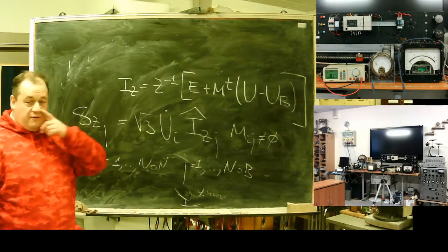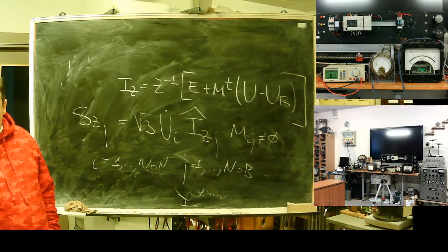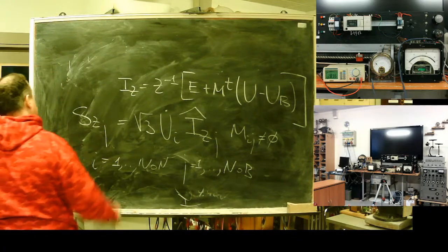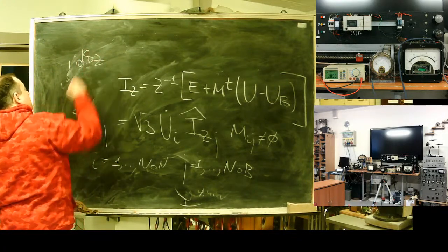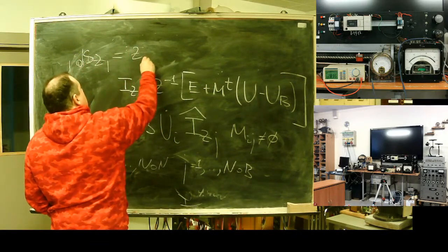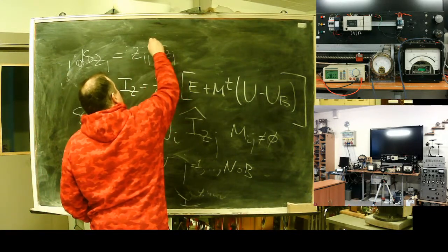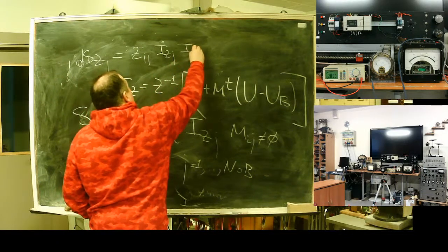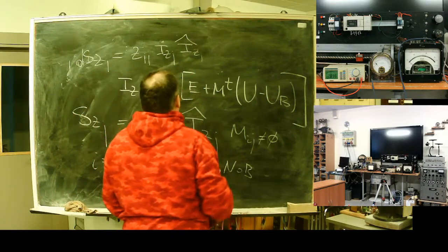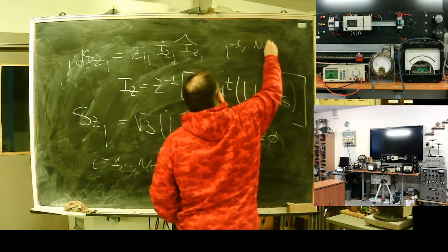Square root because we have line voltage and three phases. If you need losses, branch losses are resistance multiplied by branch current and multiplied by conjugated branch current, for k from 1 to number of branches.